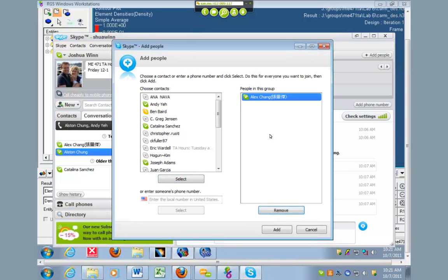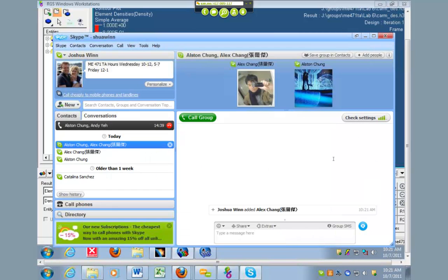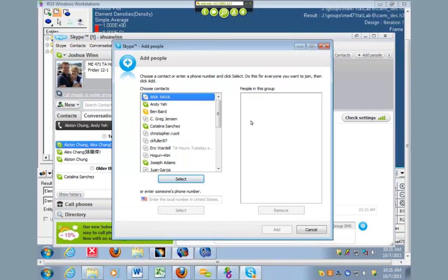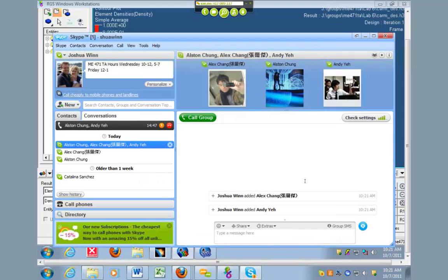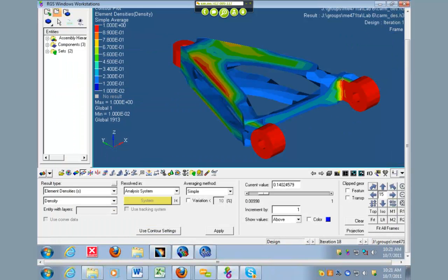So if you have accurate loads and you know exactly what loads and constraints your part has, you can run another optimization afterwards. Dr. Jensen's probably talked about this, a size and shape optimization. That one will then tell you, okay, now you should add more material over here and less over there. If you already know what your geometry is and you want to make some parts thicker or other parts thinner, then that other one will do that. So there are multiple phases of optimization you can do to end up with a good result. So at this point, you just pick a good ISO value you think looks pretty good, basically.